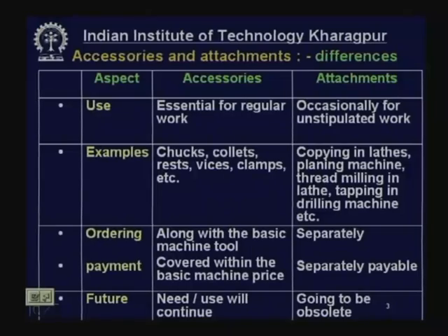You have to do milling, say long thread milling, and you do not have such a machine, then you have to use an attachment in a lathe. Besides that, very quick and vast advancement is taking place in machine tool sophistication, versatility, automation, and especially flexible automation like CNC and machining centers. As and when these machines are coming up, the need and use of attachments are gradually decreasing.